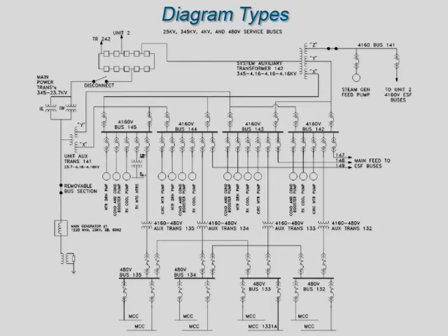This electrical single-line diagram depicts the major power sources, breakers, loads, and protective devices, thereby providing a useful overall view of the flow of power in a large electrical power distribution system. On these power distribution single lines, even if it is a three-phase system, each load is commonly represented by only a simple circle with a description of the load and its power rating.